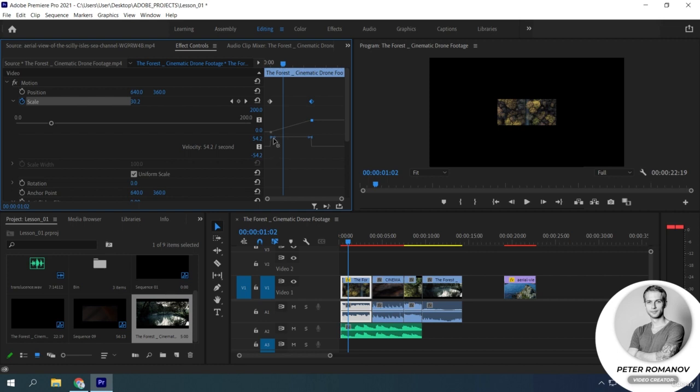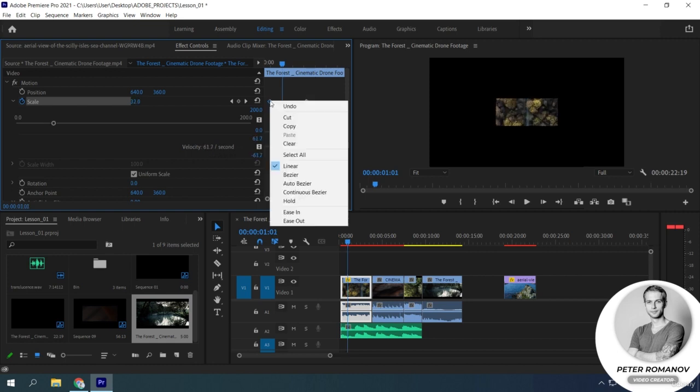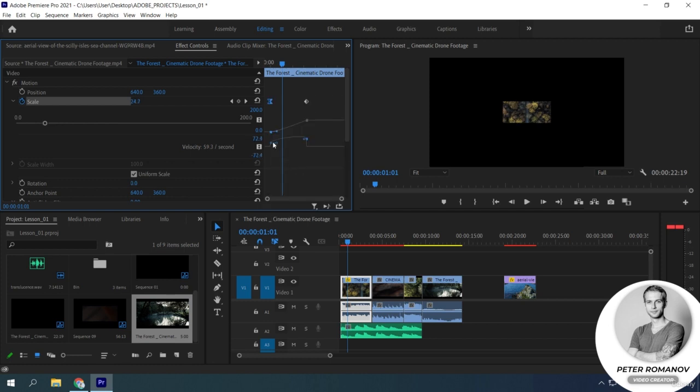We can view the settings using the right click on the desired point. Each point has a time interpolation. In this case, the linear mode is selected. The parameter changes constantly. The speed is unchanged. If we switch the mode to Bezier, we get the following. We have tendrils that allows us to change the curvature of the line and the speed. With this function, you can make a smoother, sharper appearance of the frame and adjust its speed.